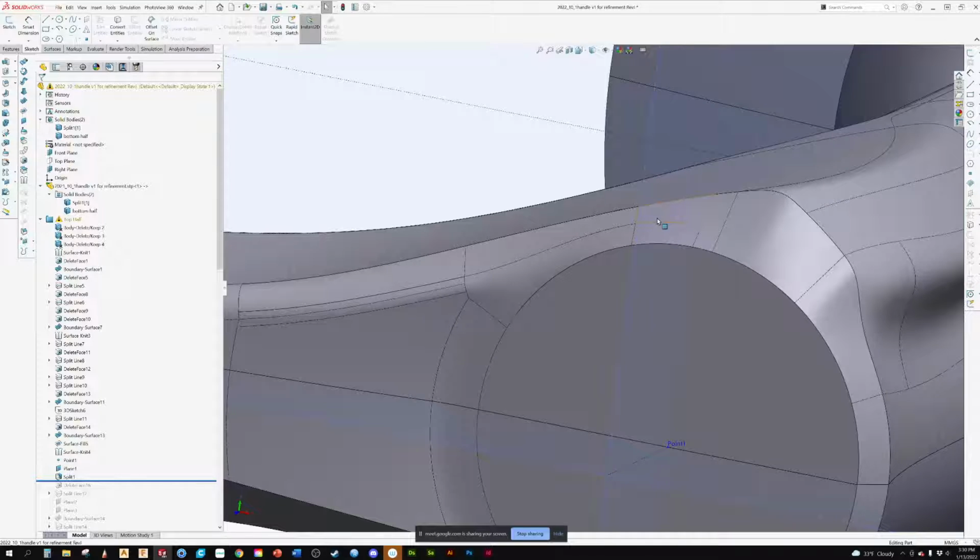So I'm not overbuilding and then trimming back. I'm using existing edges to sweep the surfaces. So I'm not trimming anything. When I do that, that means I have to pay very close attention to how clean this surface is, how clean this surface is, and of that nature.